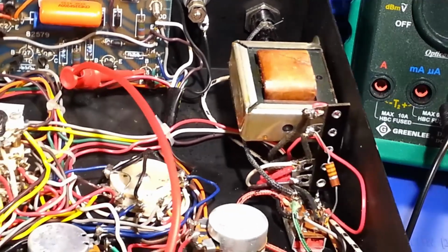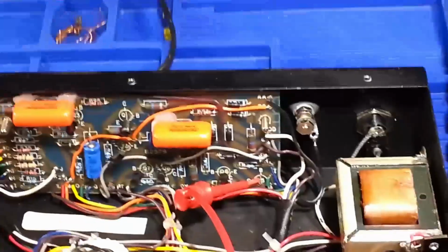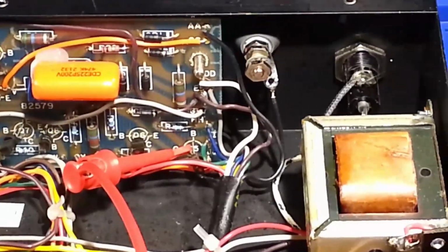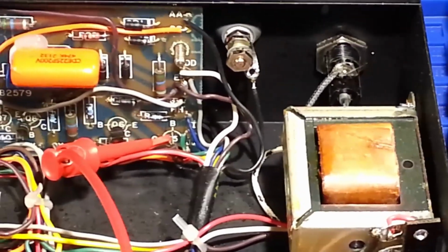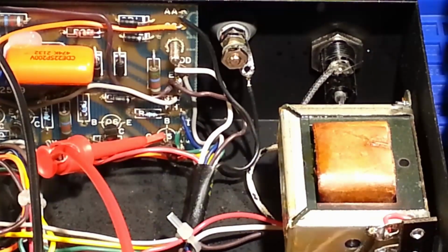So I'm going to locate Q7's not too far away from that one. It's off to the left of the view screen there. So that one should go to and have continuity through a 5.6 k ohm resistor. It does not. So that connection is suspect.